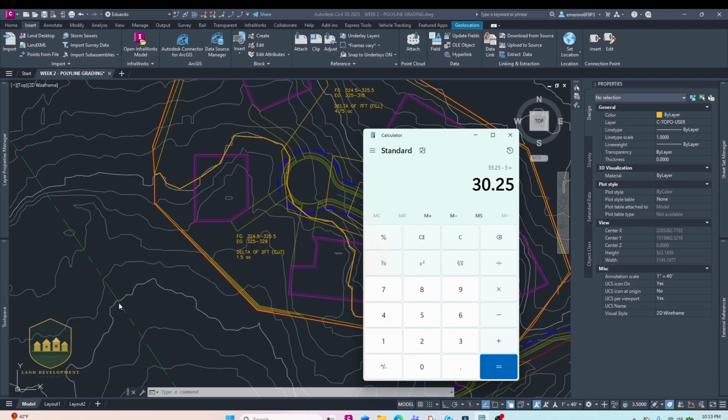Now this number is tiny because we're using acres. So let me go ahead and convert this to cubic feet, and contractors normally prefer cubic yards, so we're going to divide by 27. Now we have 48,000 cubic yards. And I want you to pause and think what this means. That means we have to import. We have so much dirt that we need to create this development that we have to ask other contractors who have a lot of export, or hire people to bring dirt into our site.